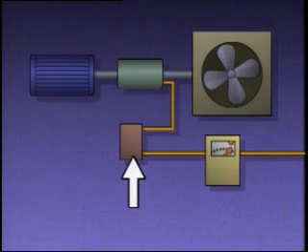When the supply of air from the fan needs to be changed, a signal is sent from the controller to an actuator connected to the coupling. The actuator adjusts the coupling to alter the speed of the fan, which changes the amount of air supplied to the system. In this topic, we saw how a control valve can be used as a final control element.